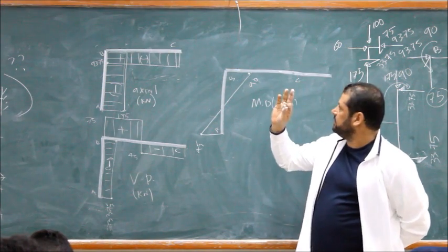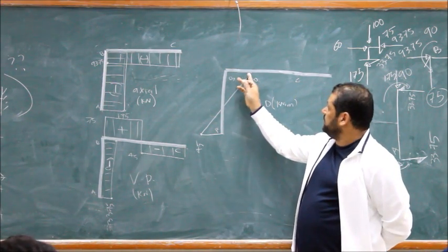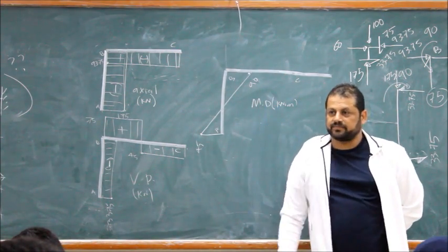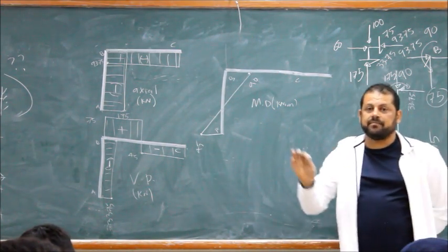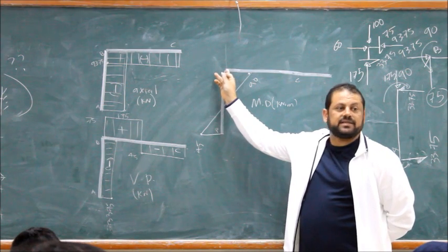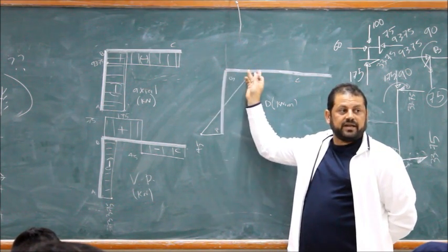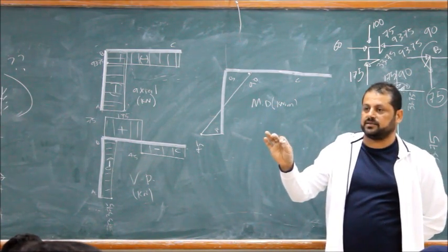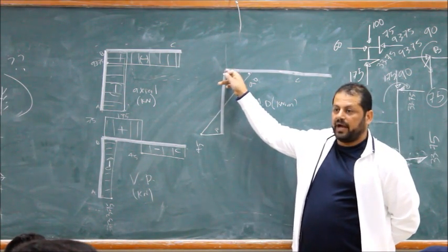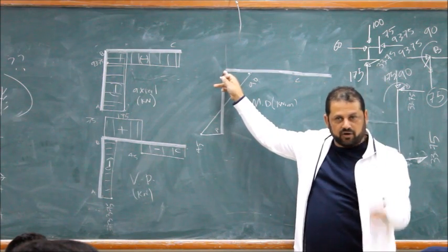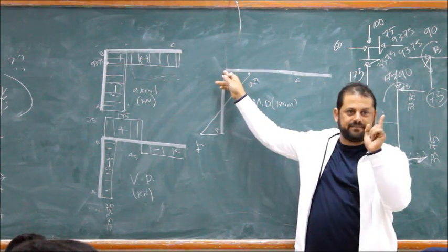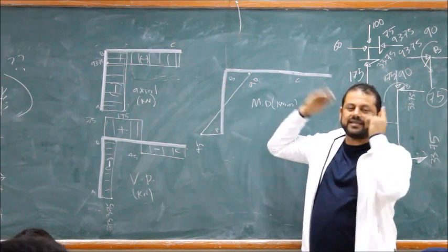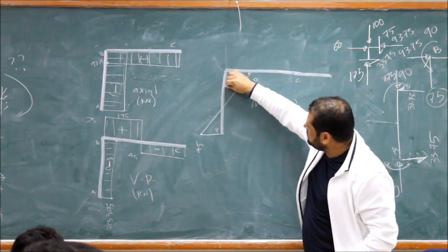Look, immediately. Negative 90, right? The same. At this joint, the moment is the same. Negative 90 is negative 90. This is conceptual in structural analysis. The moment at this joint, either in the column or in the beam, is the same. Or at the joint, negative 90, negative 90. So right away, you close your eyes, you go 90.